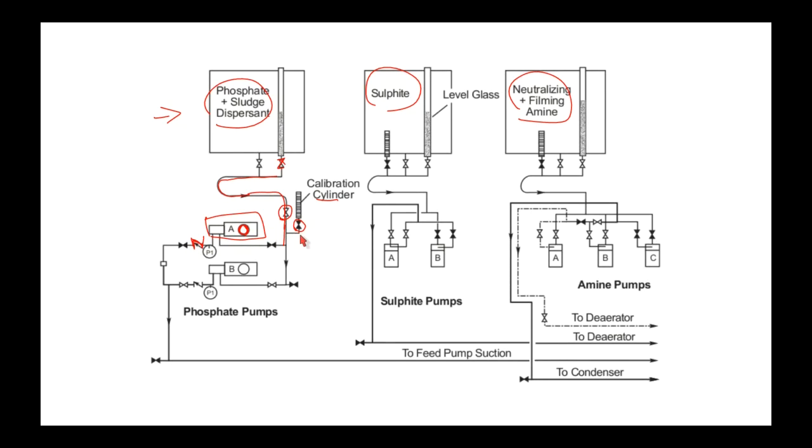So what I do is I take my little stop-start timer, and I'm going to very carefully open up this valve here and watch the level come up to its 0 mark, at which point I'm going to shut that valve. Now I got the timer ready, and I'm going to flip the valves and start the timer, and over a period of 30 seconds, I'm going to see how much it draws down.